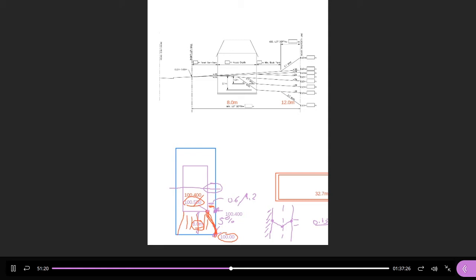Then I'm going to come down, right? I've just designed this elevation here. Look at the cross section. I've got this elevation here now. What's the elevation at the opposite corner on the lot line? What's this elevation going to be? If I come from the front to the corner of the house at 5%, I'm going to go down this much. What's the elevation on the side of the house in the lot corner? Yeah, I'm going to subtract 15. So this elevation becomes 100.250. Everybody with me? So now, what's the slope from this point to the front?